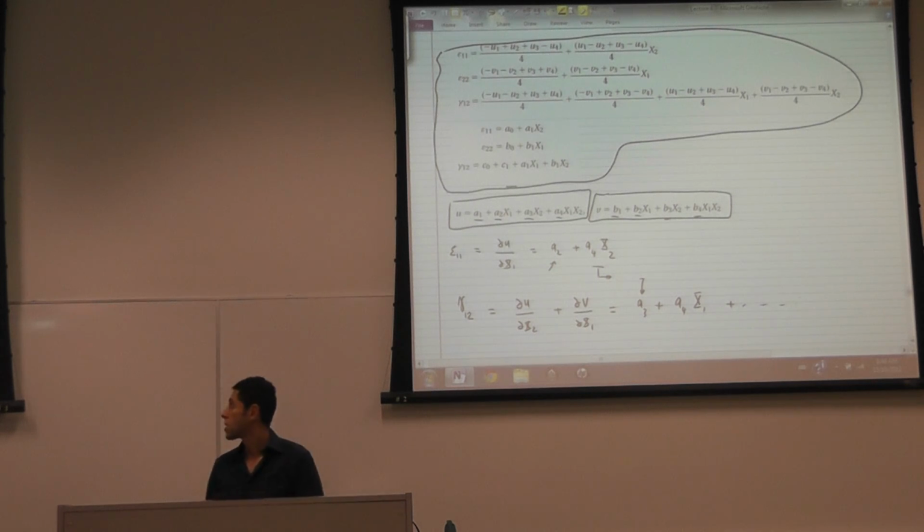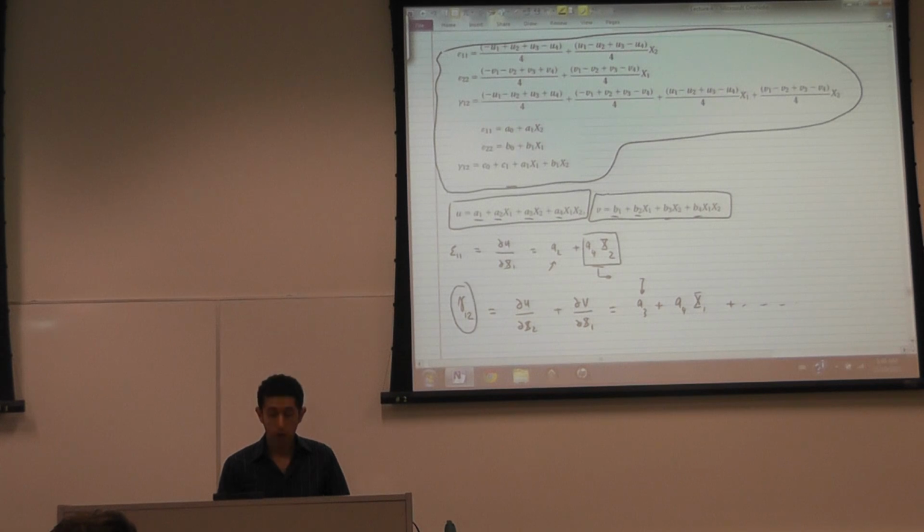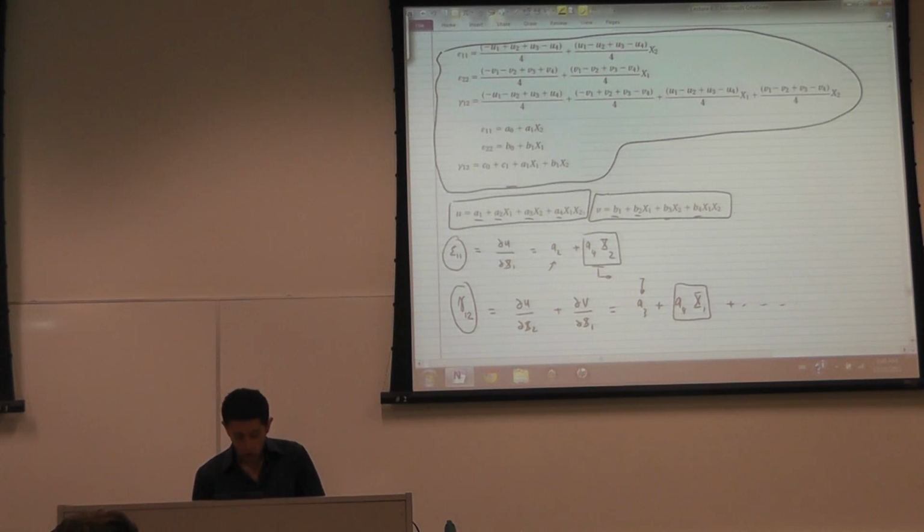So what do you notice here? That with any bending, if a4 is not 0, the element will have to exhibit a compounding shear strain. Whenever you try to model pure bending, the element will see some shear strain.